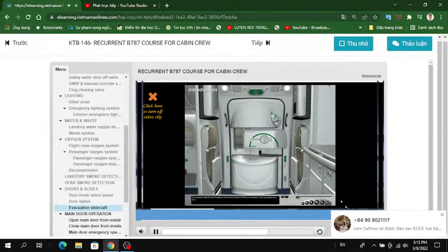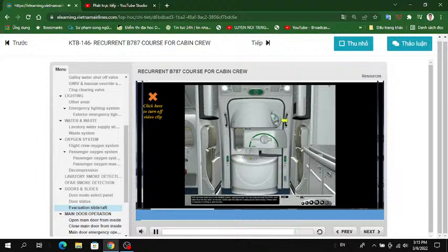An evacuation slide raft and emergency power assist system (EPAS) are contained in each passenger entry door. A door bustle on the lower face of the door covers the slide raft. With the mode select lever in the armed position, opening the door from the inside activates the EPAS, which helps drive the door open. As the door rotates open, the slide raft is deployed and automatically inflates within 10 seconds of starting to open the door.